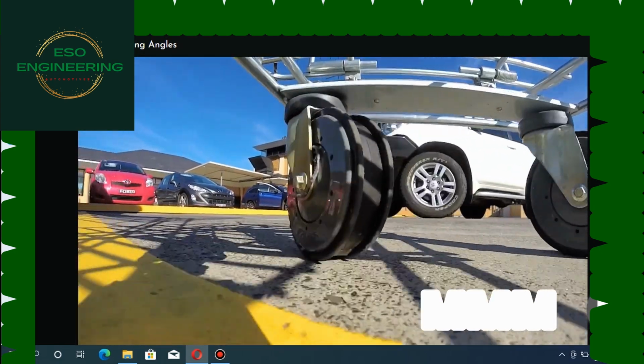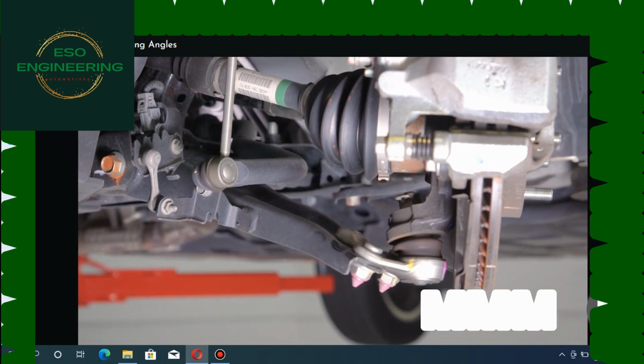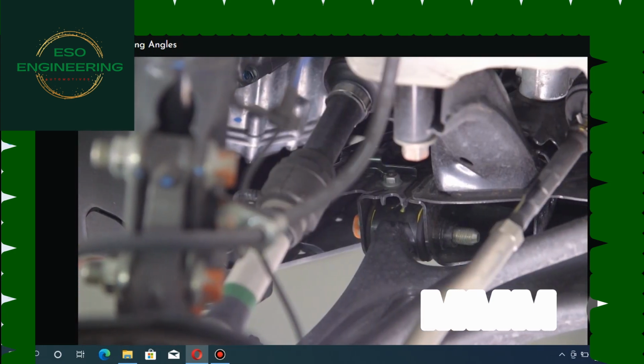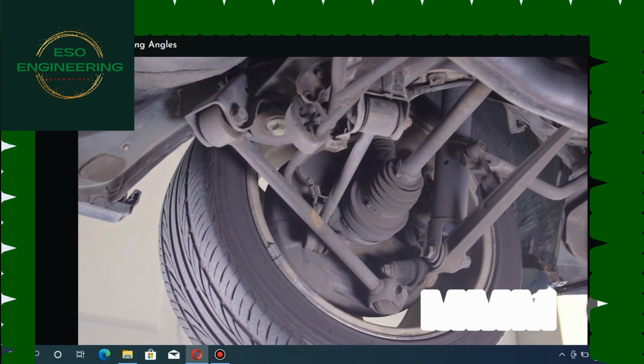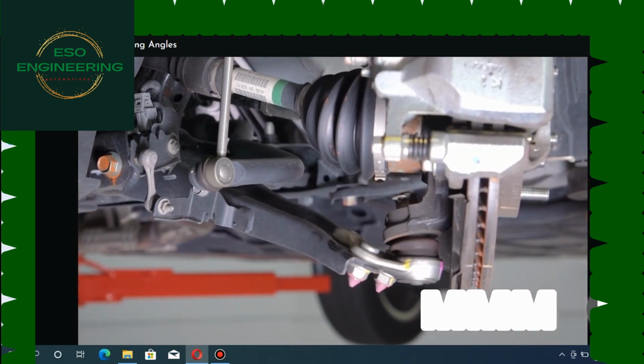heavy or unresponsive. Caster angles may be affected by worn or loose ball joints, worn control arm bushes, and worn or damaged radius rod bushes. The result of incorrect caster is not normally associated with tyre wear.